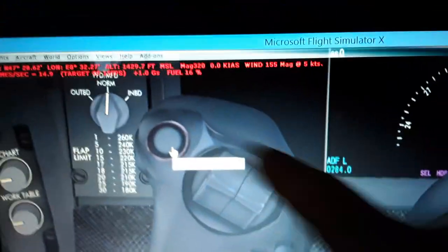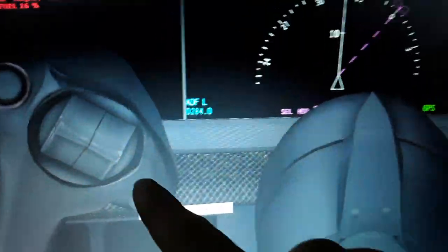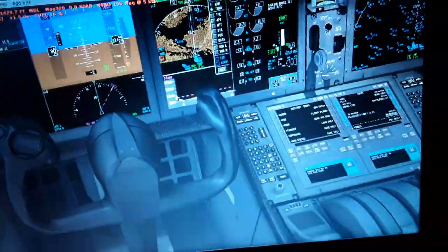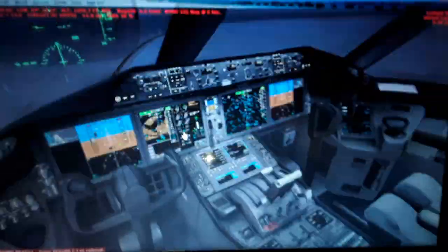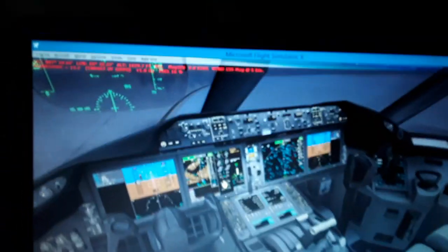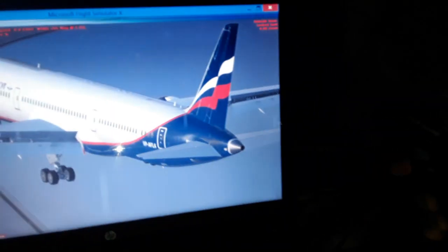So this way you pitch the aircraft nose up, this way you pitch the aircraft nose down. You have the head up, also the clutch and the autopilot disconnect over here. This switch, the flaps also, speeds. So we have a fly-by-wire aircraft. It has flight control computers. So this is how to trim the elevator up. You will see we can move the elevator also using the side stick here for climb and for descent when flying.